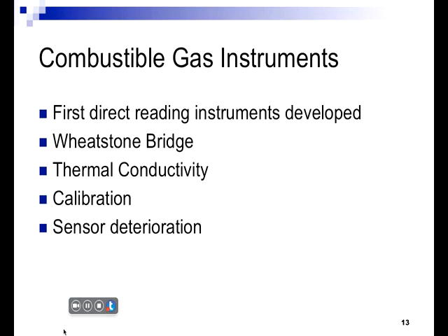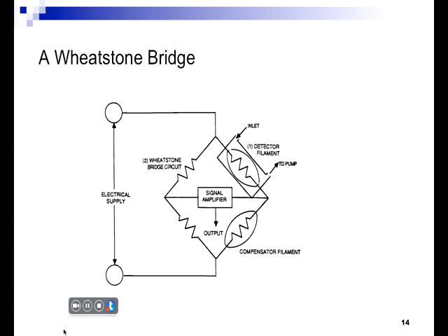And in the case of monitoring gases and vapors, it actually does matter, because you're going to have to calibrate very, very sensitive differences. And so calibration is real important. You have to calibrate these each and every time you use them, because the sensors are changing over time. It's kind of like a moving target, because that wire is going to be changing, just like the light bulbs in your house. And one day they'll actually deteriorate to the point they can't be used anymore.